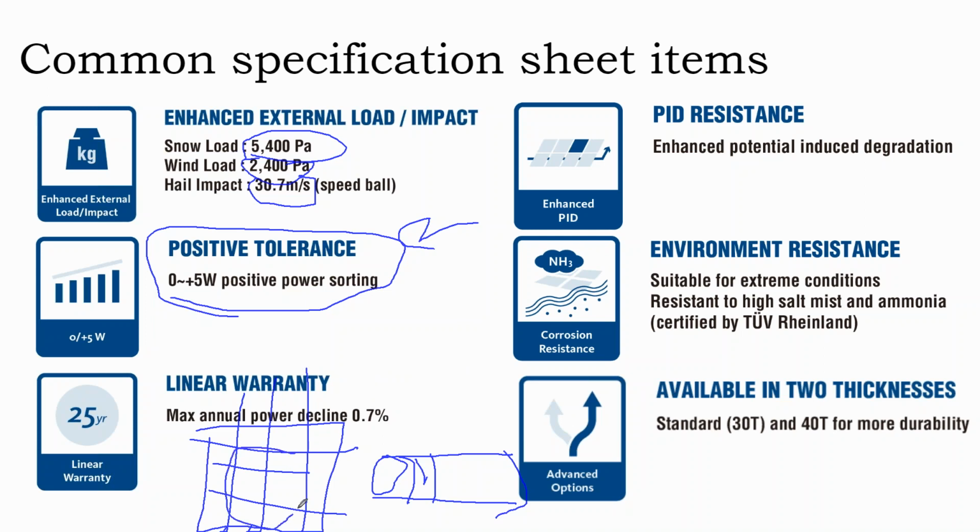The short of it is the interior of the rectangle or the interior of the cylinder is more pure than the edge conditions. So it used to be they would take these slices of silicon or slices of the sheet and just throw them onto the solar panel, and it would have this big tolerance. Nowadays, they test the cells before they make the panels, and the more efficient cells go onto the more efficient panels, less efficient cells go onto the less efficient panels, and that's why you will get one spec sheet listed for 250 watts, 255 watts, 260 watts. It's because they're doing the cell sorting. They're making all these different wattage modules out of the same production batch.